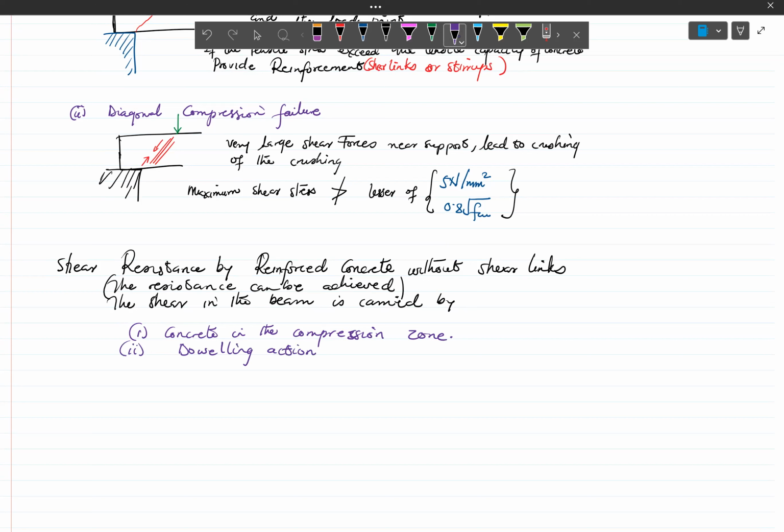All right. And that has to come from the tensile reinforcement. Okay. So this tensile reinforcement is a longitudinal reinforcement. All right. So when you find your AS, and then you place your rebars at the base or at the bottom side, that rebar can also carry some of the tensile stresses, or resist some of the tensile stresses. All right. And it's able to achieve that